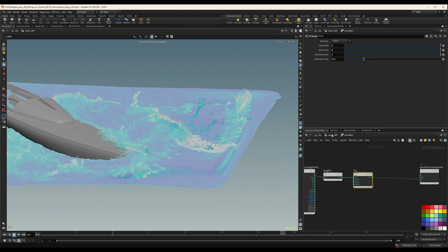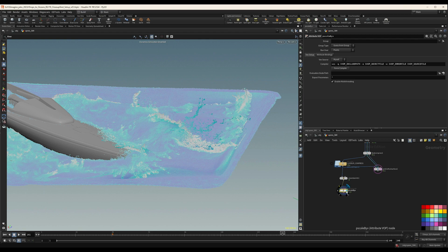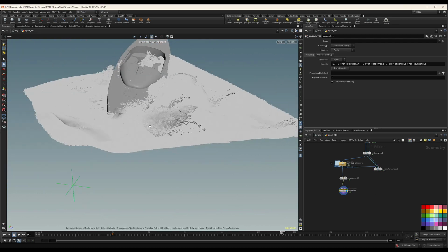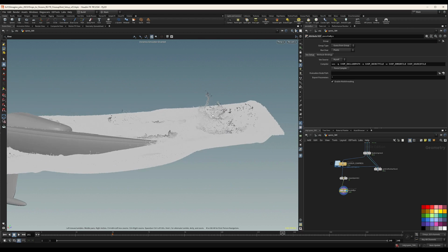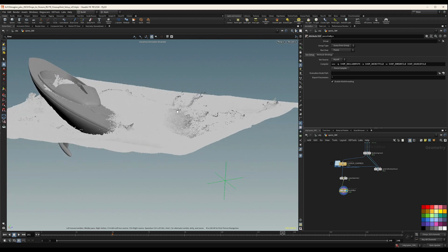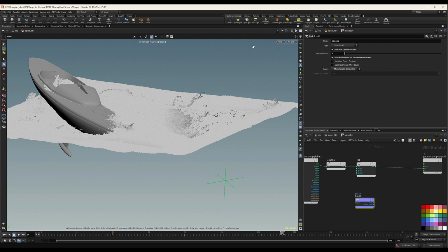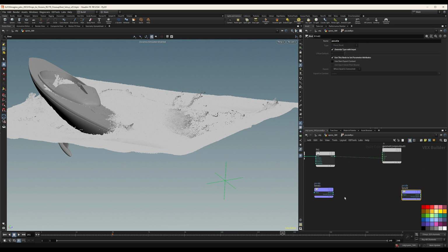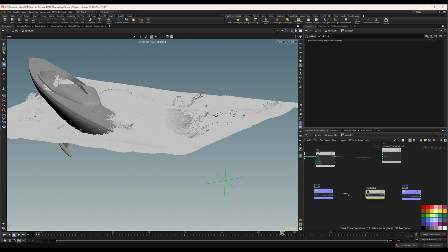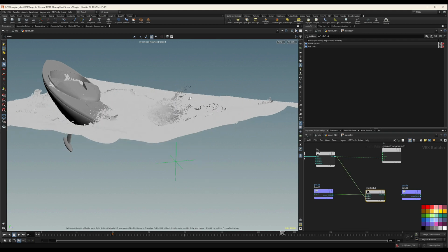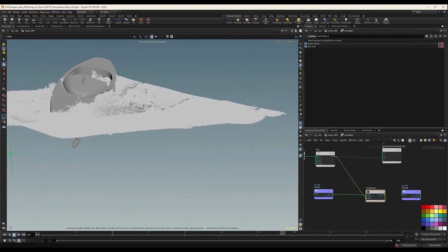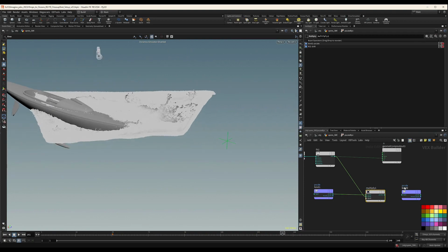Okay, something is definitely weird in here. I think it's because of that. Okay, there you go. Awesome. You see all this, it's going to decrease the P scale. For that, we're going to do the same thing. We're going to do a bind export. Let's call this P scale. And you can copy that and multiply. So we're going to multiply our P scale by this new range, and these parts that are looking black, that is faster, they're going to be 20% of the original P scale, right?